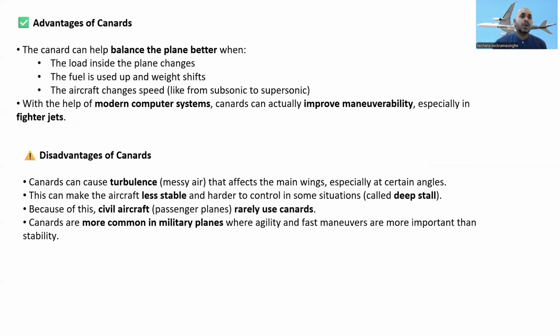Advantages of canards: they can help balance the plane better when the load inside the plane changes, when fuel is used up and weight shifts, and when the aircraft changes speed, like from subsonic to supersonic. With the help of modern computer systems, canards can actually improve maneuverability, especially in jets.